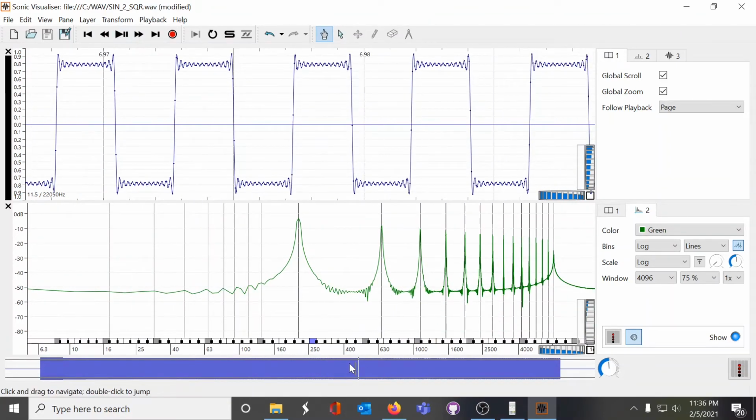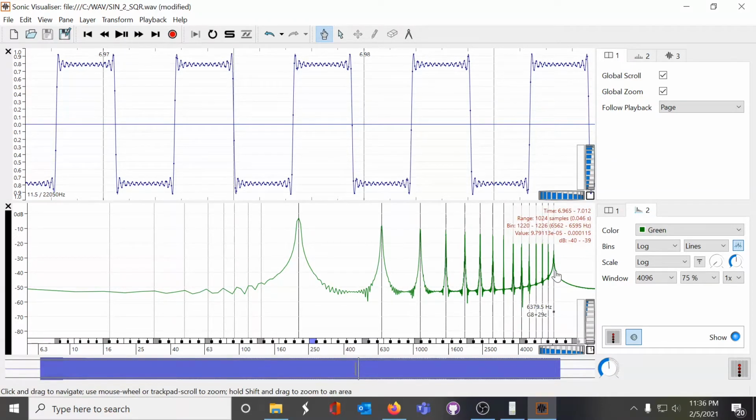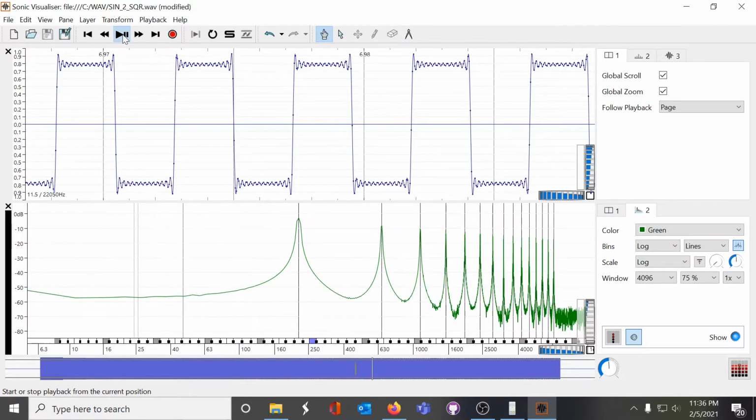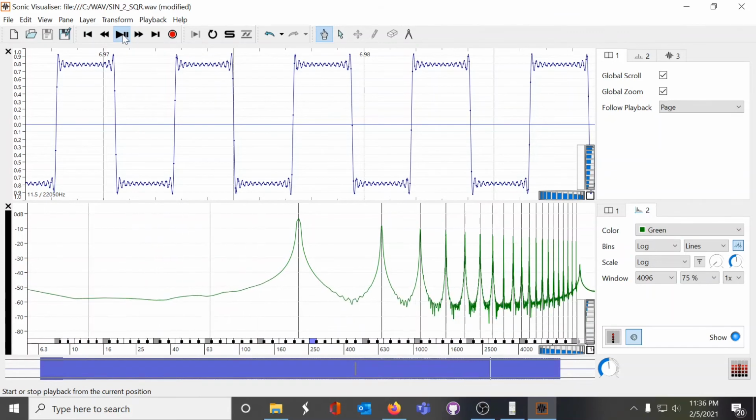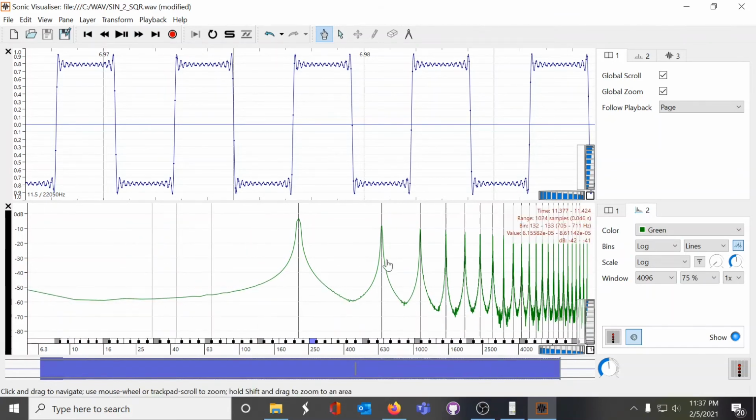We're about halfway through the music file right now, and we have arrived at 6380. When divided by 220, that is the 29th harmonic. And we can keep going until the very end of the file. This gives us a reasonably good approximation of a square wave. The edges are very steep and the top is quite flat. Not perfect, but pretty close.